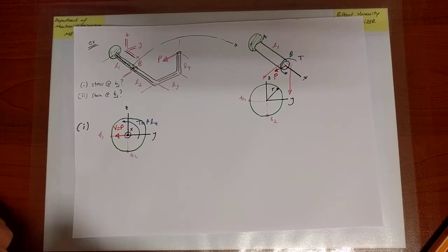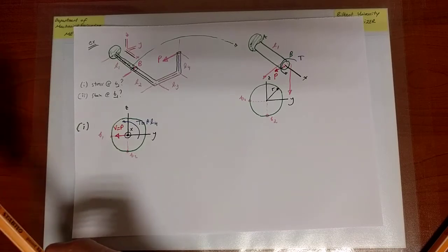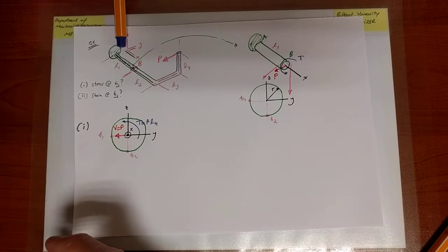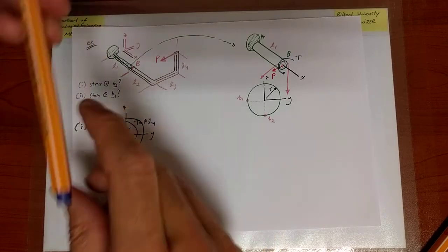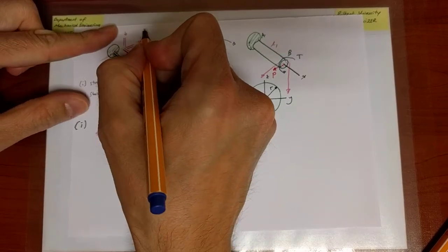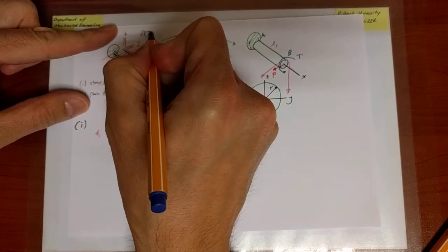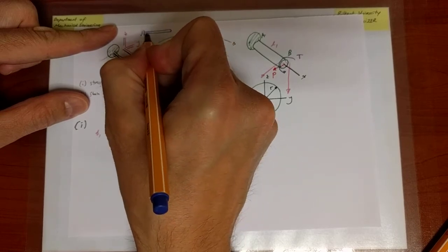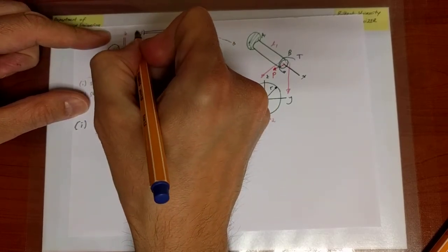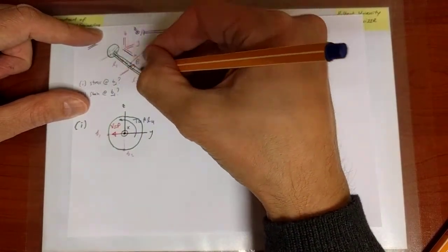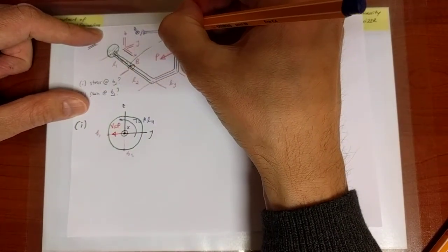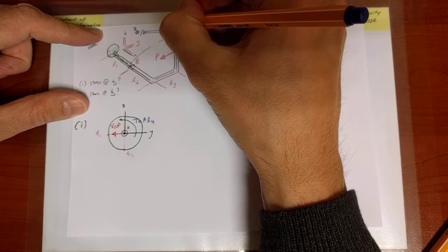And then there is also going to be a bending moment. That bending moment is going to be about the z-axis, because if I look from above, so I'm looking in the minus z direction, I see a beam that is supported, and it is bent like this.